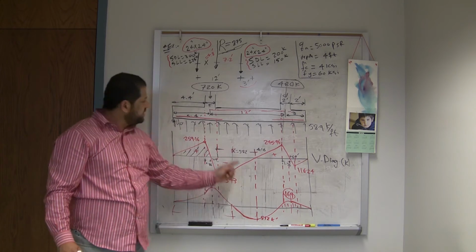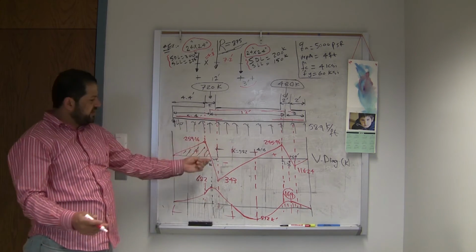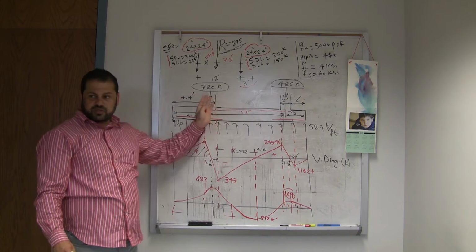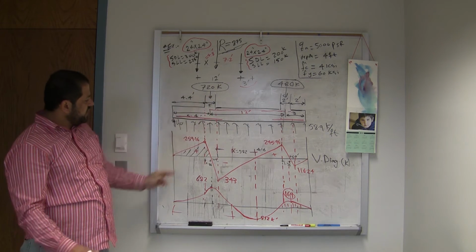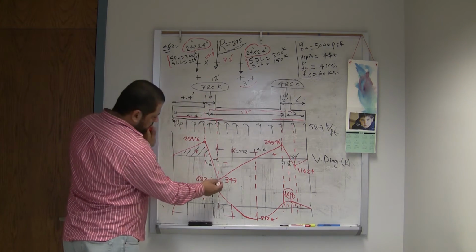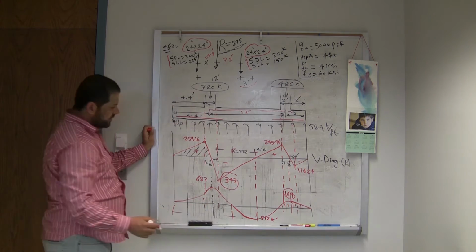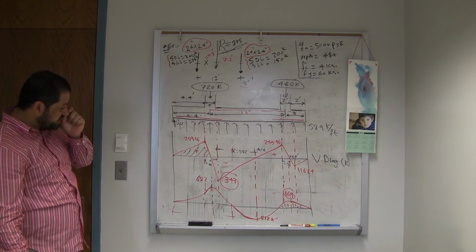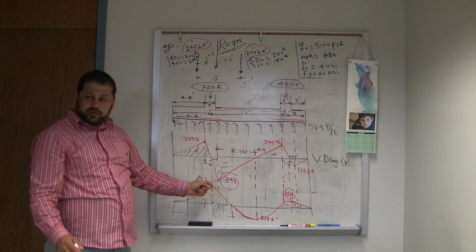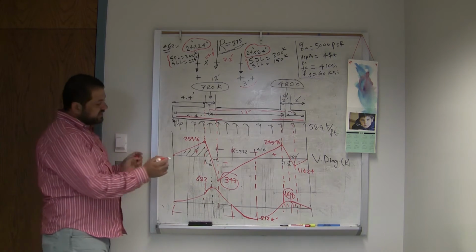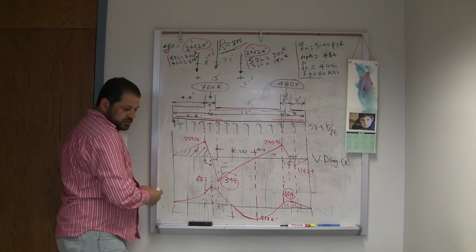Now we need to calculate, before we go there, the reinforcement is easy to calculate once we have D. So now we have D. So the ultimate shear is, we have this 343 at the face of this column. We know the critical section for the beam shear is at D from the face of the support.